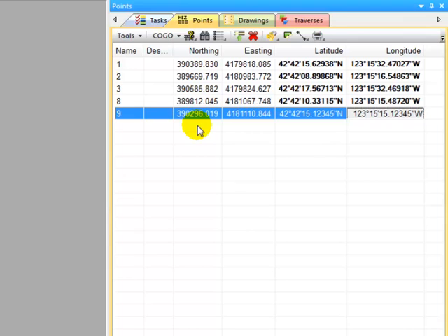And the preference then here, the thing that we call preference, is that you can see the latitude and longitude are bold. Traverse BC is going to hold those positions no matter what. As needed, or when it needs to, it will update the position of the coordinates based on those geodetic positions. I could do exactly the opposite. I could enter coordinates for a point, and Traverse BC would know that it's supposed to hold the coordinates and simply transform the geodetic position as needed based on the coordinate reference system.